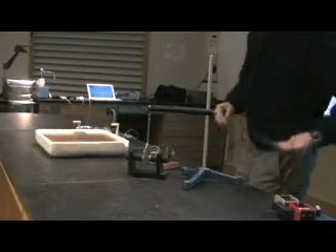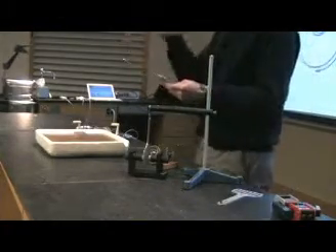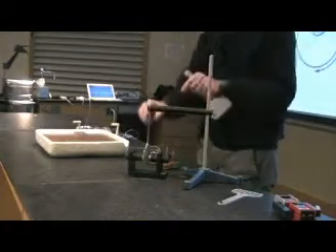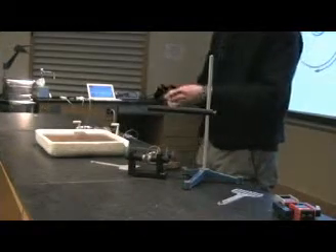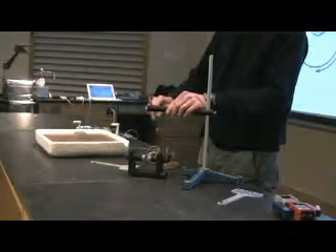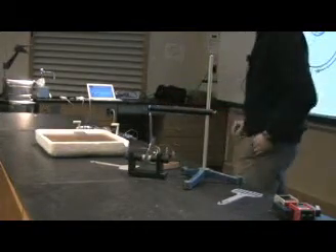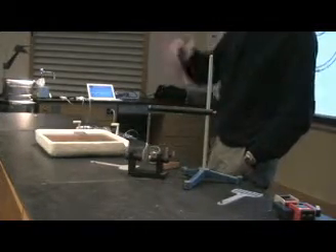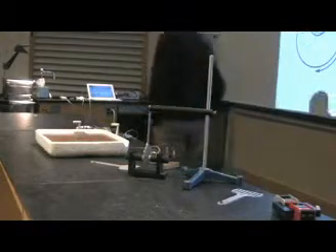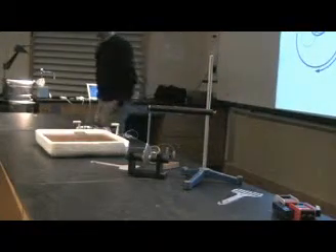And then we saw the other day that if you cut these slots in the aluminum, you can't get those big swirls. And so this one actually isn't nearly as affected. It's got almost as much aluminum as the first one, but it's not nearly as strongly affected as the first one because we've cut these slots in it and then we can't get these big swirling currents that set up the big fields that interact with the field of the magnet.